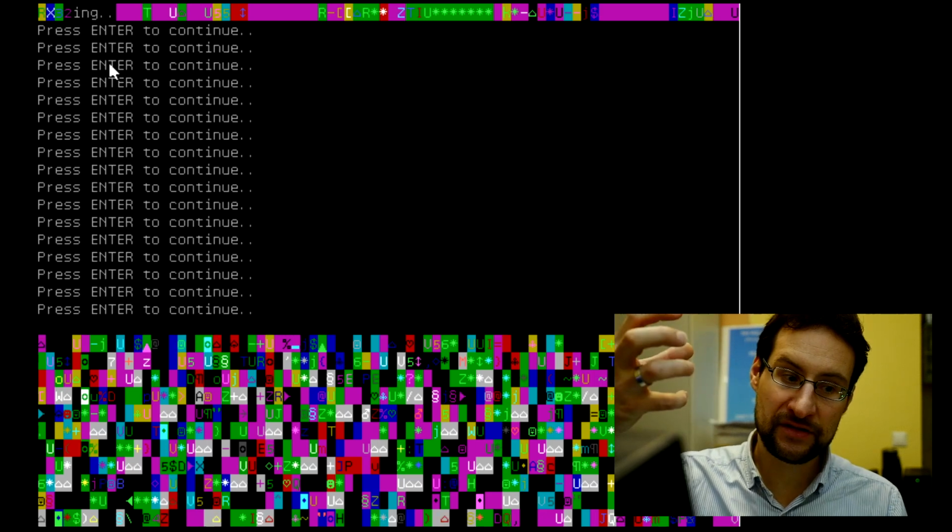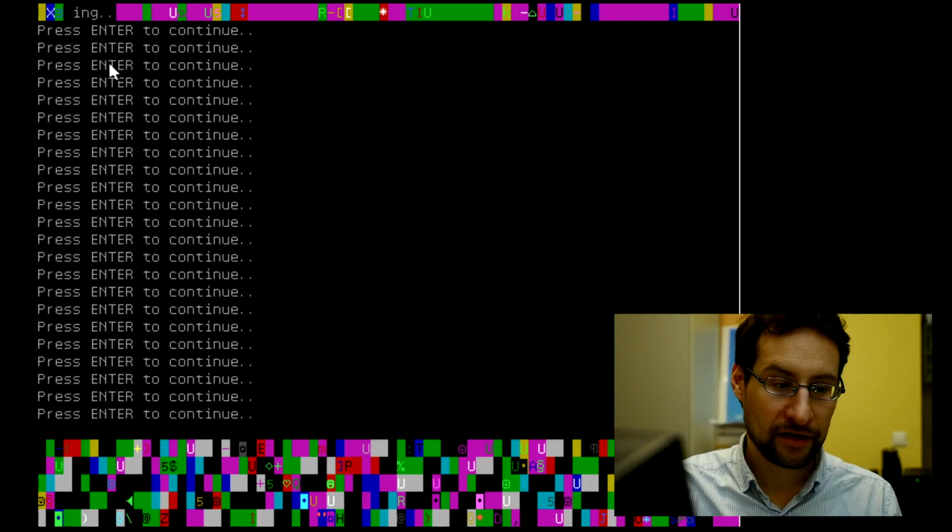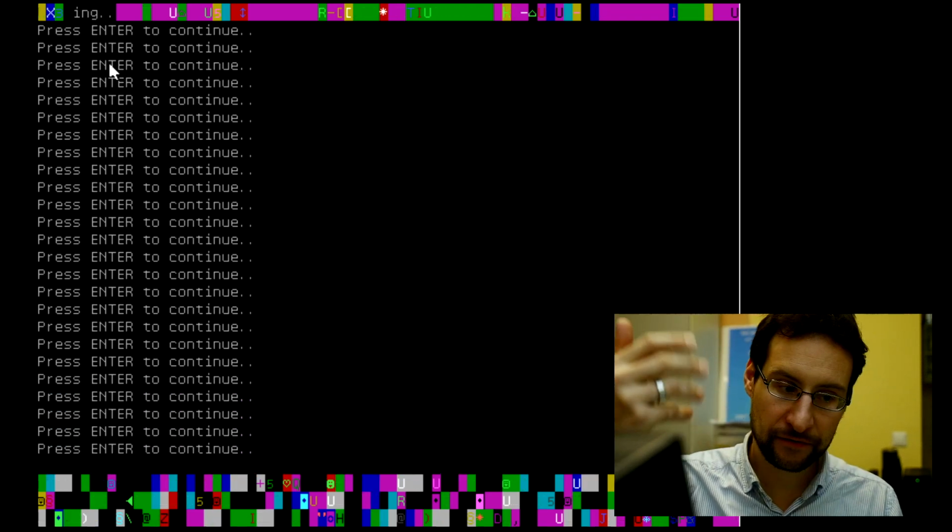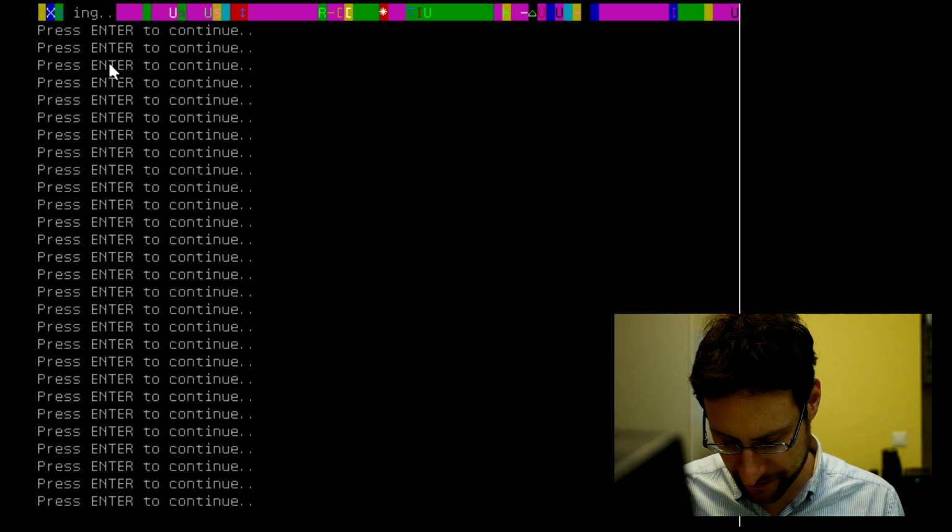We are coming in. Actually, when we boot up, this random pattern is not a random pattern. If we quickly switch to graphic mode, this is actually preloading Lena with this initialization. So the FPGA bitstream has initialization for the Lena in graphic mode and the character sets, filling the frame buffer, VRAM and character set.